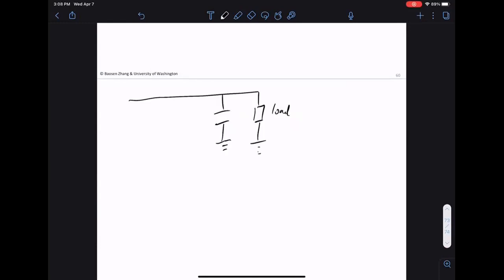So this is similar to impedance matching I saw in the chat. Your load changes, the P and Q of the load changes, so you cannot have a fixed capacitance. That will also create problems. Having too much reactive power is also bad because something has to consume that reactive power. So your voltage cannot be too low.